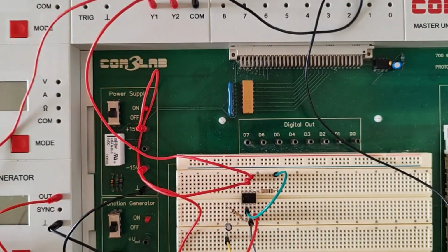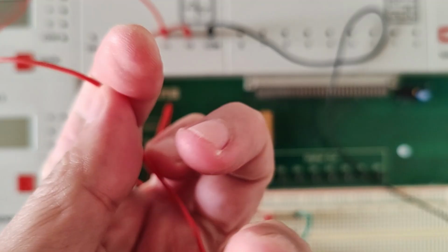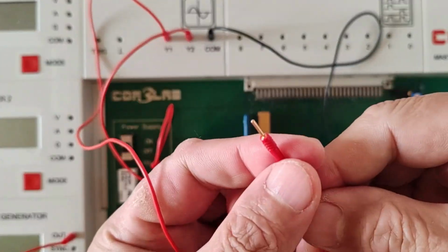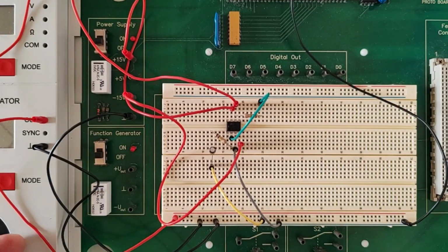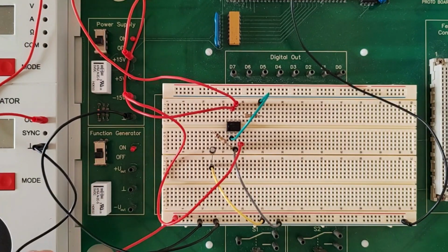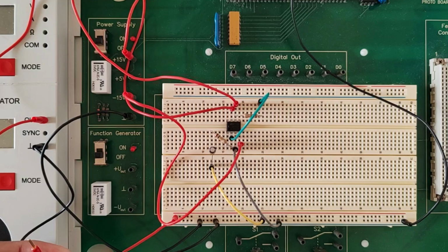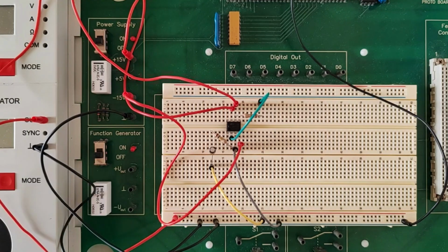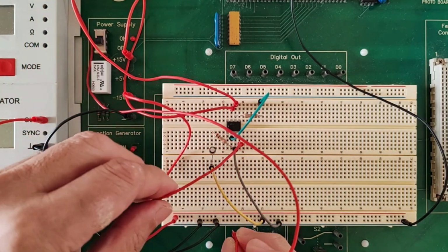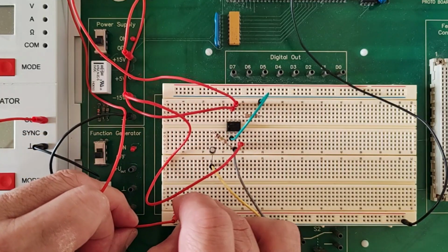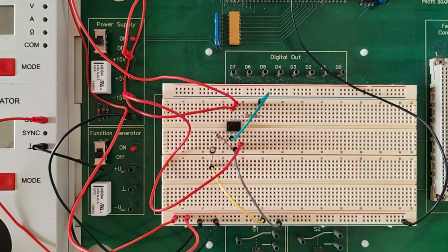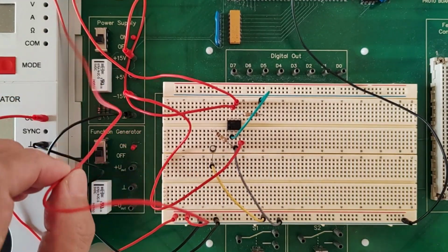Now, lastly, we need to connect also Y1, this one. We're going to use Y1 of the oscilloscope for input. So if that's the input, I'm going to connect it to where the function generator out cable is connected, which is here at the bottom rail, red side, the bottom rail. Let me do that now. Here. So we're here down. There. Input is there.